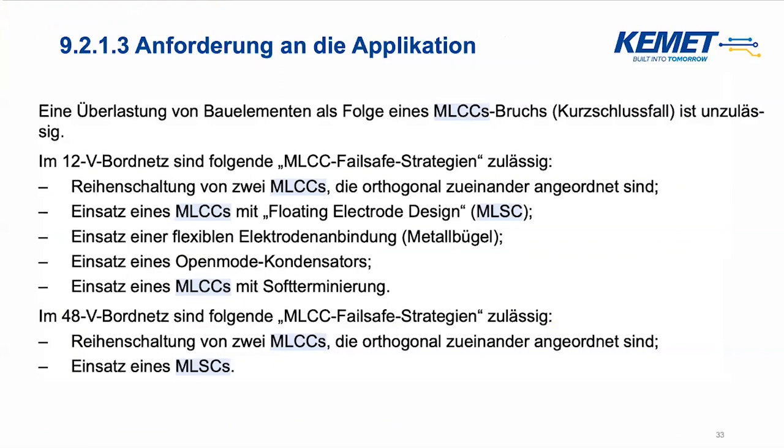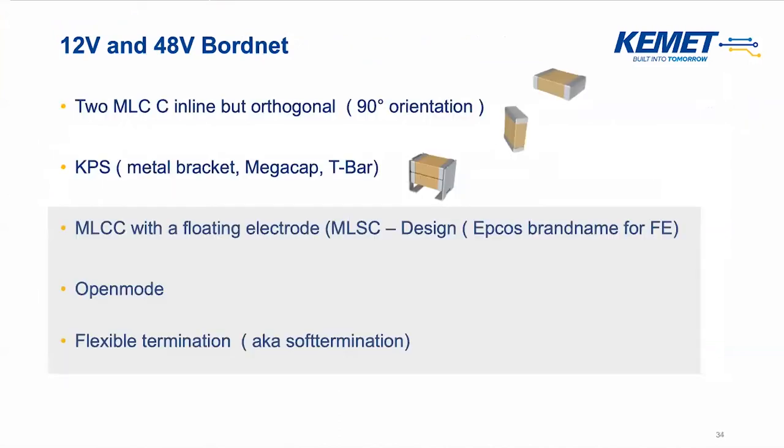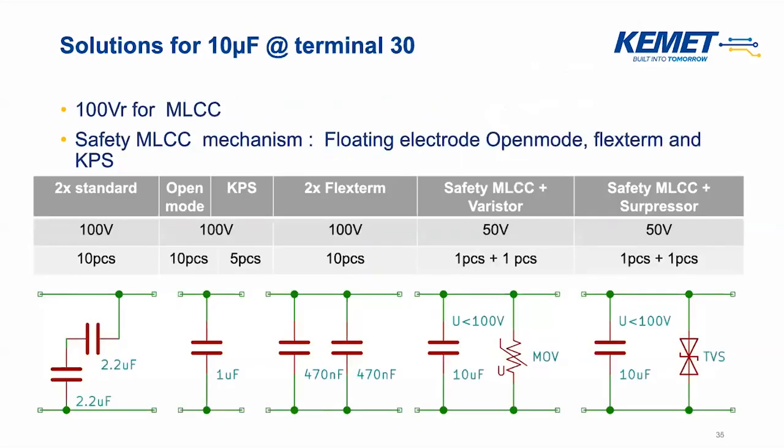Again, so that's a requirement for the application. The German text, because there's a lot of non-native German speakers here in the call, we can skip that. It's just saying that we can use 2 MLCCs, or you can use a floating electrode or open mode or something with flex termination. Because not everybody is aware about KPS, that's the metal bracket, or some other words going around in the market are megacap, T-bar is also an expression for that. And then you have MLCC with floating electrode, open mode, flexible termination. That's your offering in the 12 volt or 48 volt net. That's the kind of product you can use in there. And I think we have that already.